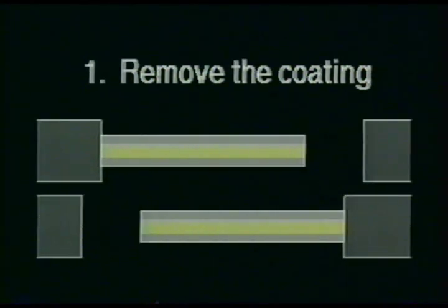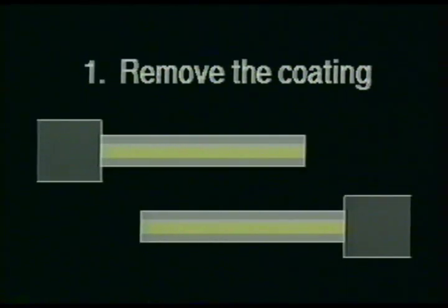First, the ends of the fiber cables must have their protective coatings removed. This exposes the bare fiber cores. Next, the fibers are cleaved to the proper length and polished. Then the bare fiber cores are placed into the fusion splicing machine where they are aligned and gapped to the proper setting.